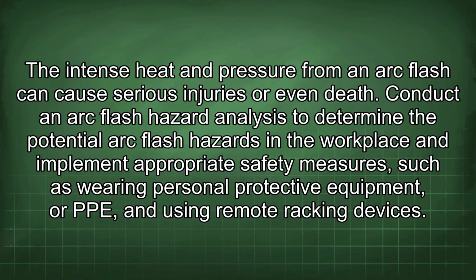Conduct an arc flash hazard analysis to determine the potential arc flash hazards in the workplace and implement appropriate safety measures, such as wearing personal protective equipment, or PPE, and using remote racking devices.